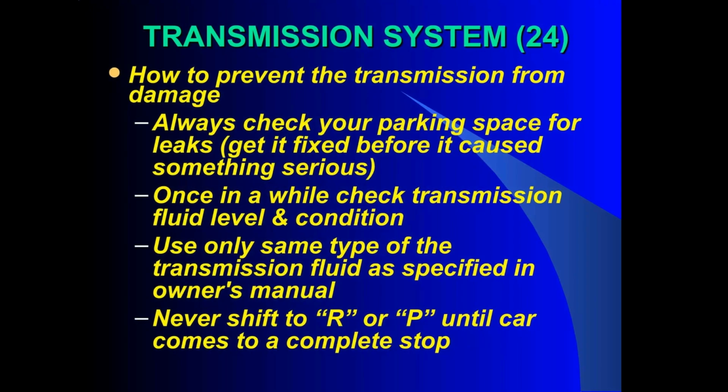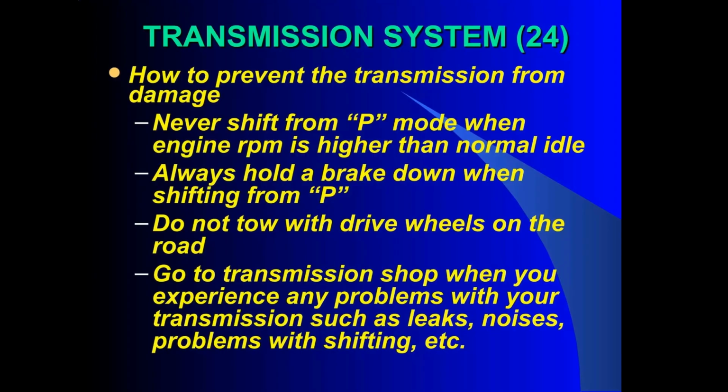Symptoms of a failing automatic transmission include the inability to shift into a specific gear, delayed shifts, slipping between gears, or the transmission making noise in neutral or park. You may also notice the engine stalling after a shift, the transmission getting stuck in one gear, or unusual noises while driving. These are signs that maintenance or repair may be needed.